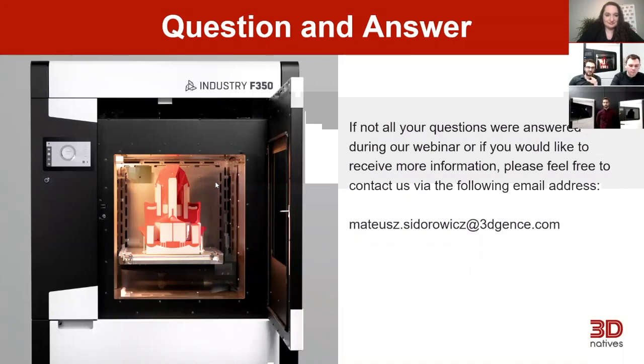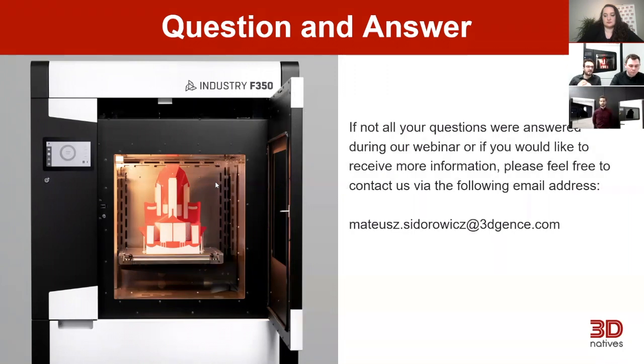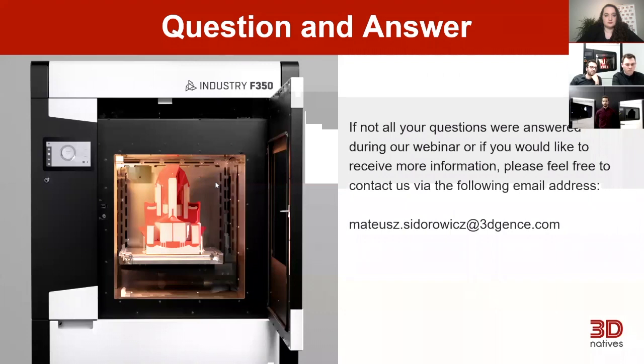Well, PA6 and PA12 are based on different monomers. They're both what we would call nylon, but this is really not saying much. It is a specific family of materials. Overall, they share some similarities, but they also differ in rigidity, toughness, tensile strength, elongation. They will display some differences. They are fairly robust when it comes to chemical resistance, but by far the biggest differentiating factor mentioned is glass fiber loading.